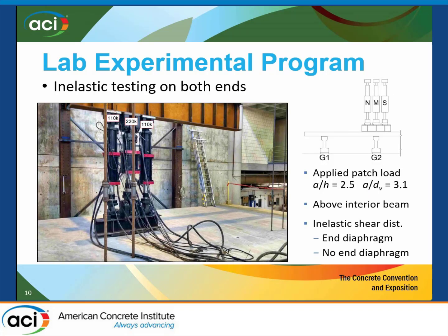Load was applied with all of the actuators we owned to try and fail the structure, which was great. But that's what it looked like, from a picture view. But really, what it's doing over there in the top right is applying all of the load over top of an interior girder, recognizing that if we apply the load elsewhere, we're just pushing down on a 9-inch thick deck, and it's not really going to do us much good.